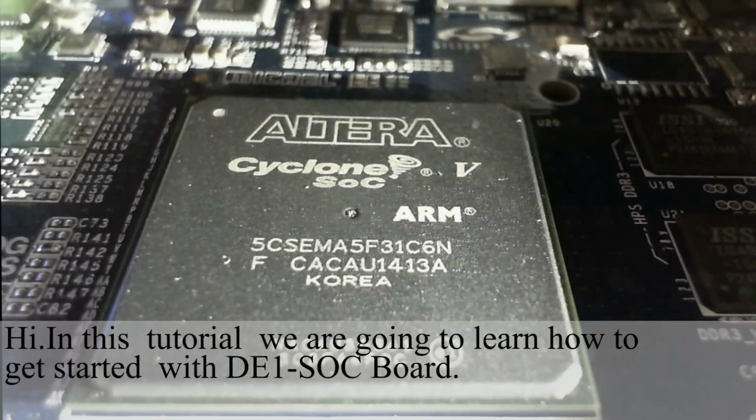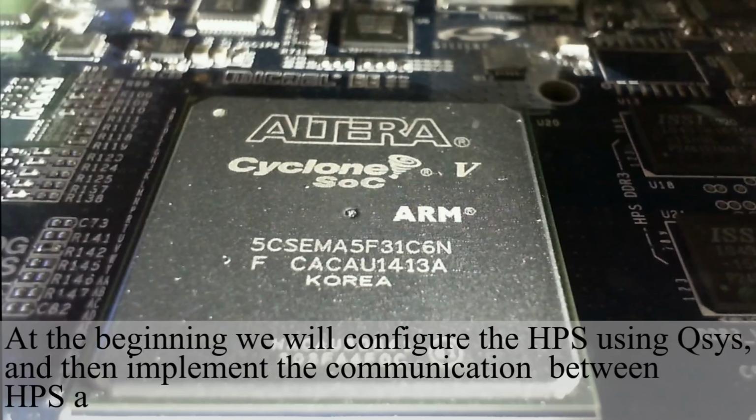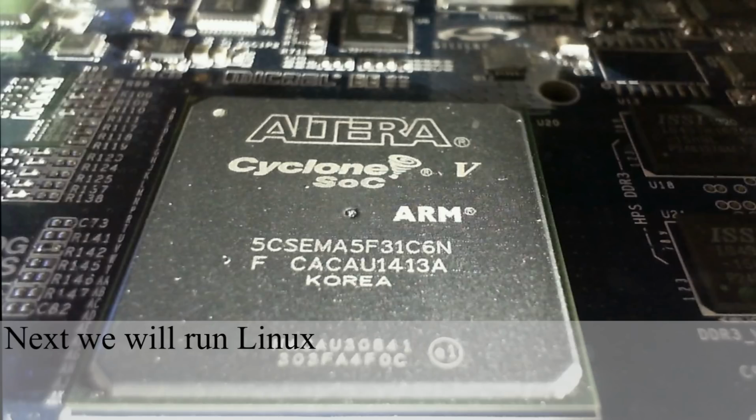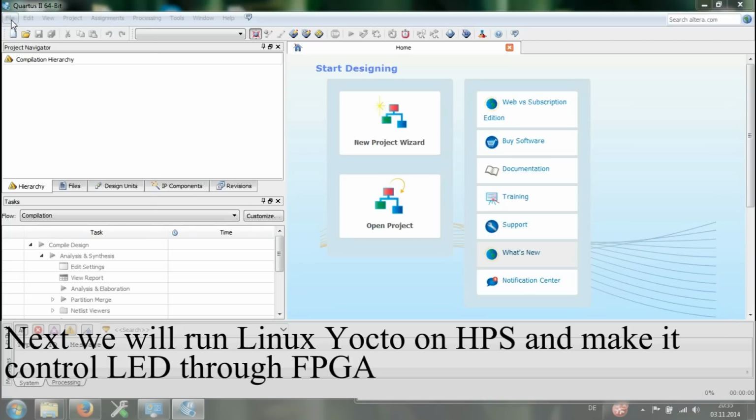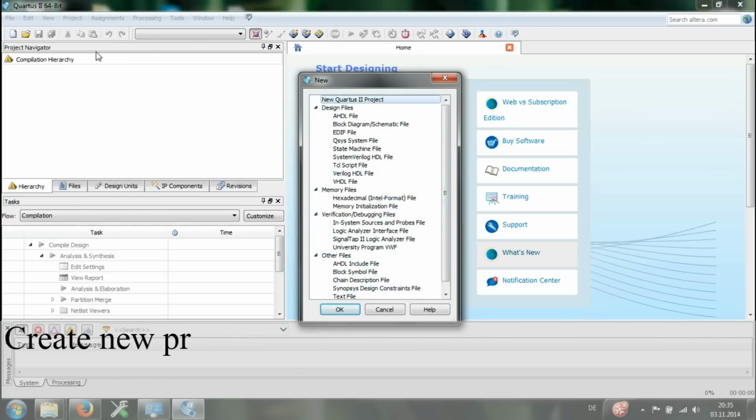Hi, in this tutorial we are going to learn how to get started with DE1-SoC board. At the beginning, we will configure the HPS using QSys and then implement the communication between HPS and FPGA. Next, we will run Linux Yocto on HPS and make it control LED through FPGA.